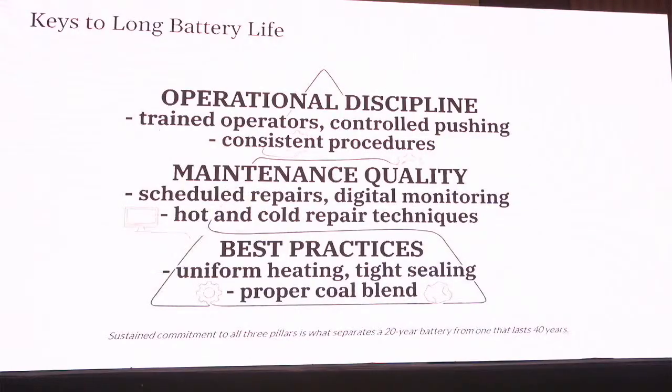Regular training to execute critical tasks such as making informed heating decisions, controlling pushing forces, and ensuring tight sealing of doors and lids. To maintain quality, scheduled repairs to be there, and digital and data-driven monitoring to be done. Digital monitoring and diagnostics help operators detect early wall cracks by shifting to a precise data-driven approach that identifies the structural issues before leading to further damage.